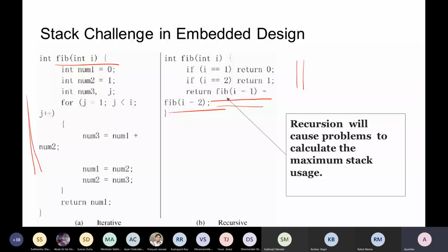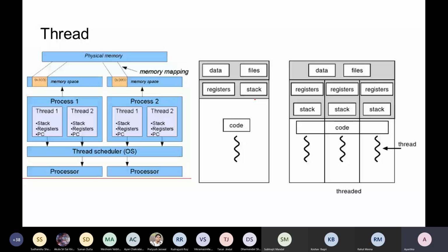Okay, so these are the few things we need to take care. The second thing is that, or maybe I should say, first one we talked about interrupt, second one we talked about the way of coding, third one when we are talking about something small processes. Like if you remember our elevator design, one is unit control, one is request resolver, or our interrupt handler processes. One is interrupt handling process and another is my main process.